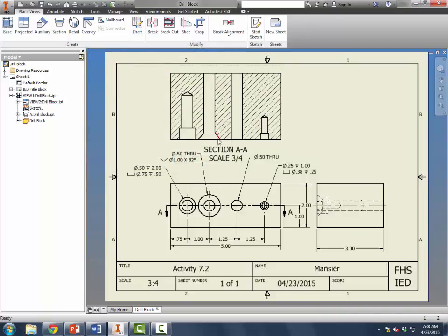Okay. So now it's giving me, if I were to cut through this object and remove the top half of this object, what would I see for the top view? And this is what I have remaining. Like we said before, because I have the 45-degree angle hash lines here and nothing here, it indicates that anything that doesn't have these is hollow, which makes sense. These are holes that have been drilled into this block.